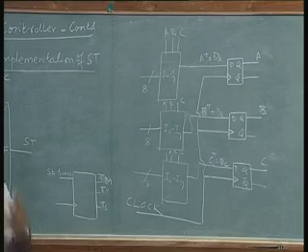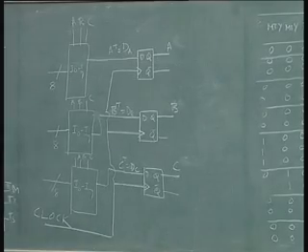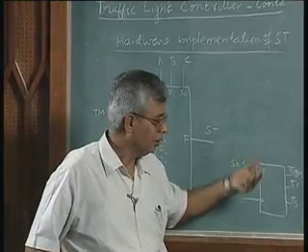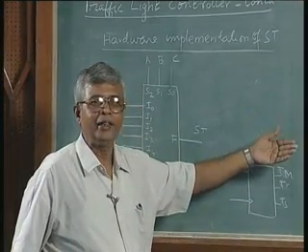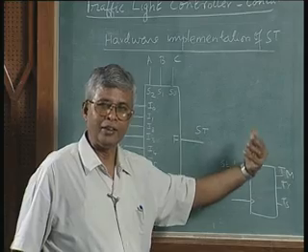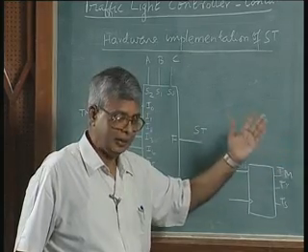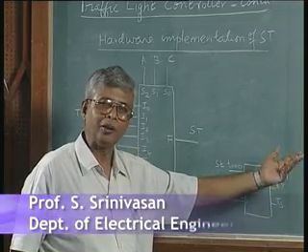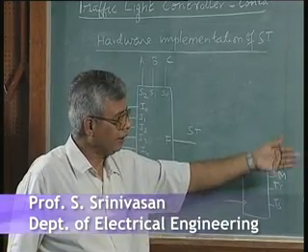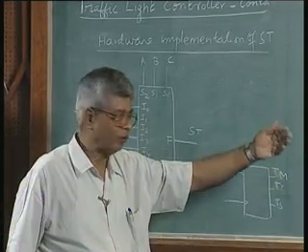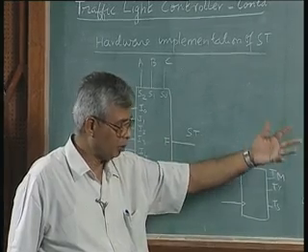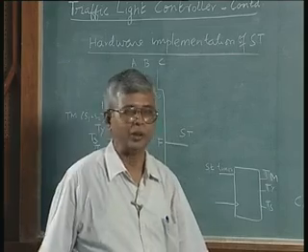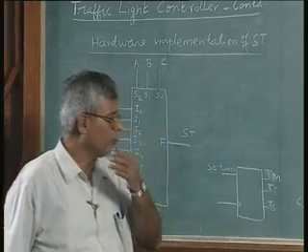So, given a problem, understand its specifications, systematic step by step procedure, call it algorithm if you want, and then write a ASM chart, identify the signals input and output for the controller, get the ASM table, get the implementation using flip flops or multiplexer or whatever, and then go to the output also using flip flops, using multiplexers or gates or whatever, and do the same thing for the outputs either multiplexers or gates, and then you have the whole problem, connect them together like this.